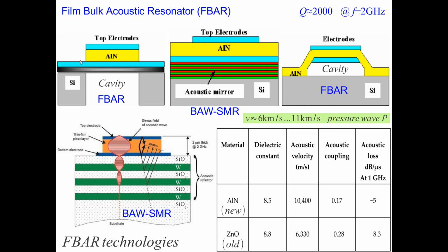They can be done as films, so we etch the silicon from below, or here I will make a cavity on the carrier silicon wafer to have our resonators. These resonators may achieve a high Q, but they cannot handle much power, because if they are heated up by the radio frequency power, this power cannot be dissipated anywhere. So the idea is to use an acoustic Bragg mirror here.